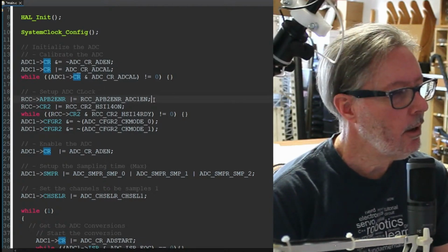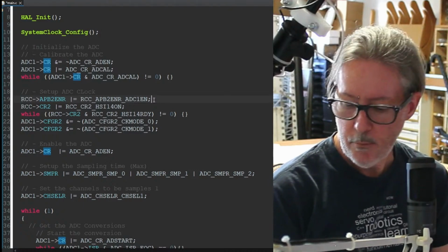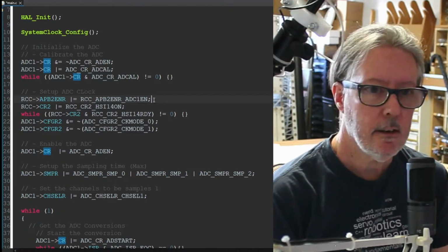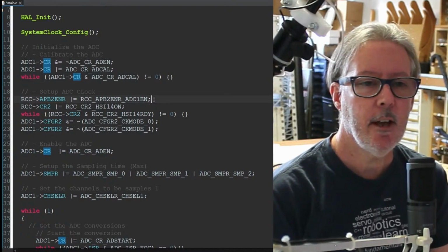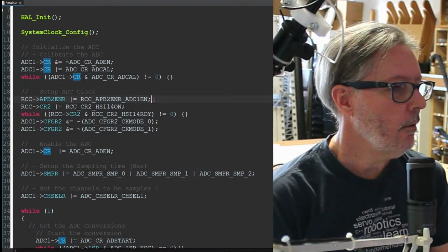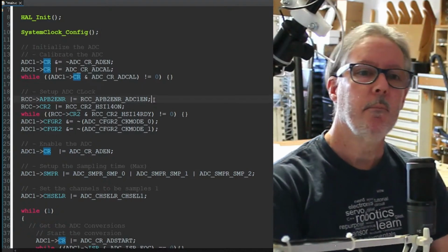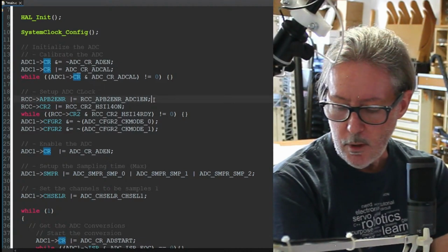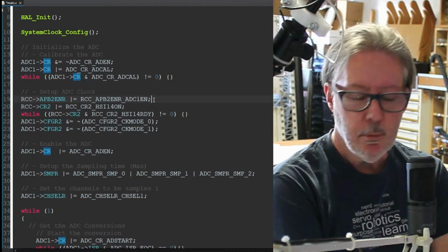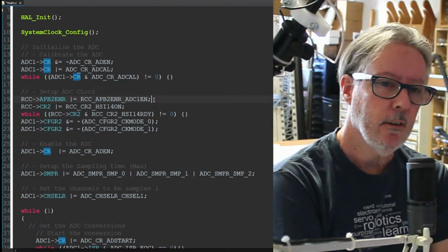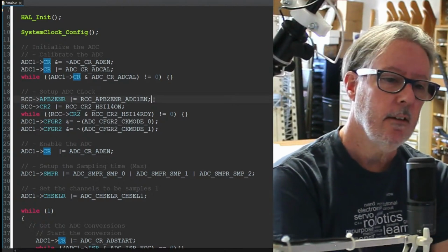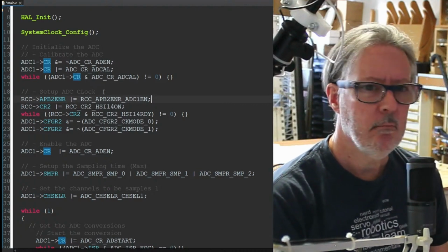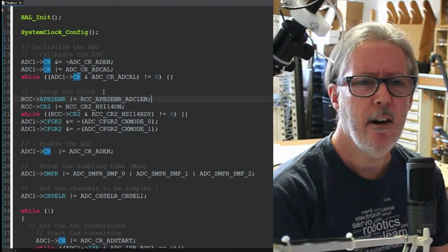But it could also cause problems with the sensor, because the sensor may not give you that much time to sample. So I can imagine a case where the output of the device or the sensor could be so fast that the ADC might think of it as just a blip or an error.